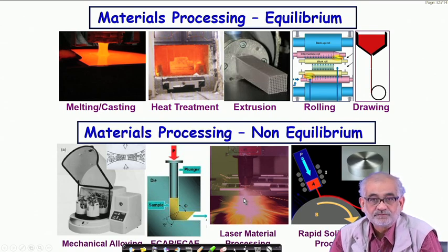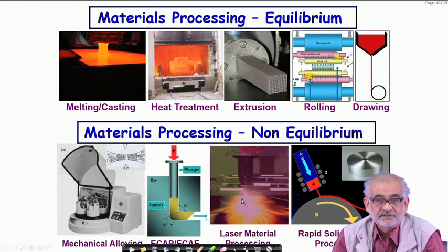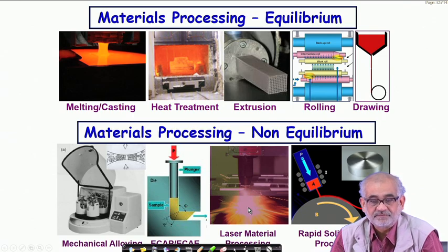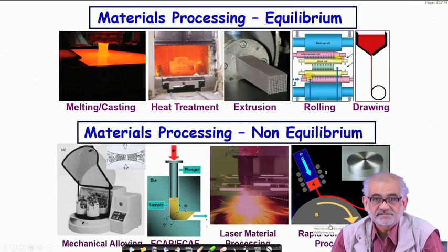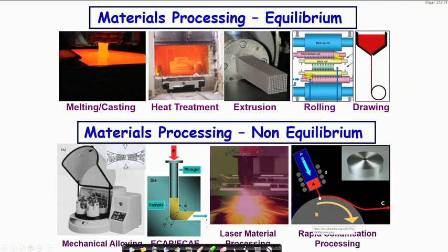We can do melting of a very small volume using a laser beam, and under the beam we can instantly take a solid in the form of either bulk solid or powders or wires into the liquid state and then subsequently quench them by self-quenching and create solid objects, gradually built from small to bigger through an additive process. We can solidify a liquid onto a rotating wheel, rotating at a certain RPM, but most importantly the wheel is made up of high conducting materials like copper, which allows very fast cooling.